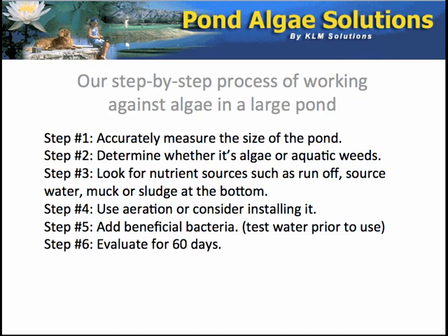Now, we would add bacteria at the proper or adequate dose, and we would do this for 60 days. In whatever form you have to add the bacteria, whether it's bi-weekly or weekly or monthly, you want to run this program for about 60 days. Oftentimes in the first 30 days with good aeration, you may see changes in the algae. It may begin to regress, or it may turn colors or whatever. But you want to try to take the pond to clearing with the bacteria.